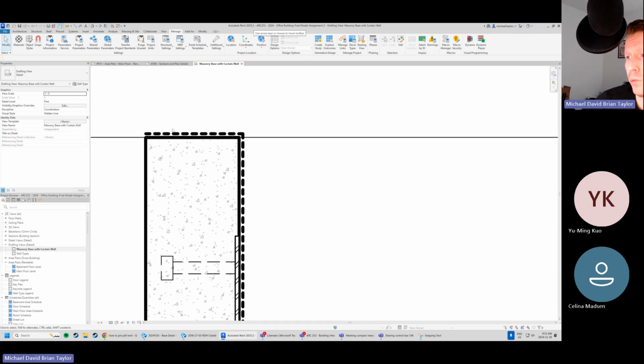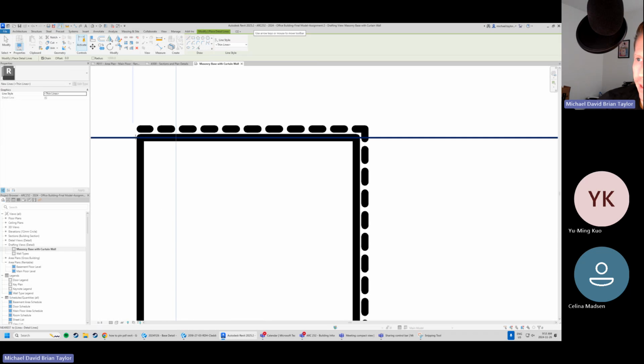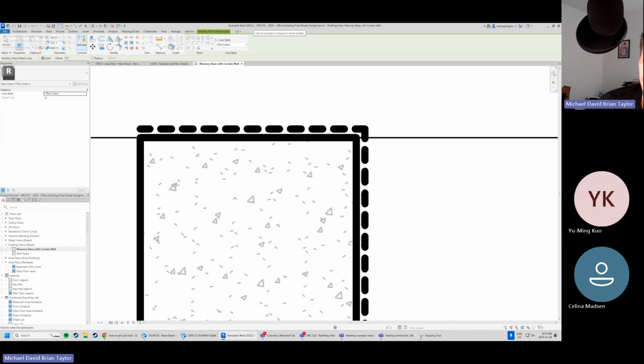Again, like I said, I got in trouble for this before. It gives a lot of detail to a drawing where you might not need it. So I'm going to do it and show you what it looks like. That detail line shortcut is DL, and I'm going to do thin lines here. And I can't remember how thick this line is.